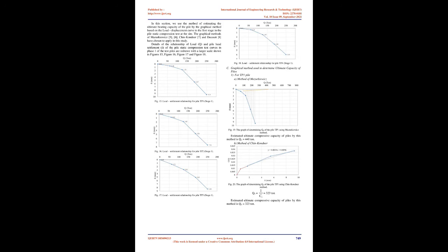At the site, 4 test piles labeled TP1, TP2, TP3, and TP4 respectively were pressed into the ground to the design depth, ensuring the maximum pile pressure value Fp max was not exceeded. The method of pressing the pile uses the load from the counterweight to create the force to push the pile into the ground.